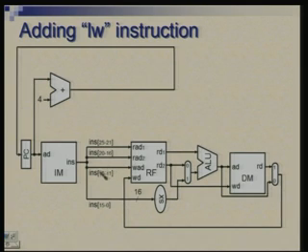So, again we need to make changes here, introduce a multiplexer, because it is either bit 11 to 15 which go there, or bit number 16 to 20 which go there. So, we have to make a provision for that. We remove this line and put it through a multiplexer, and the two choices are either this or that.